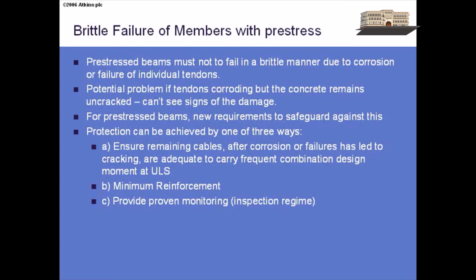As I say, if you've got very little pre-stress and a very large section, then basically when the concrete cracks, you've lost most of its capacity and there's virtually nothing left in the pre-stressing, so it might fail at the ultimate. If you don't want to do that calculation, then you have to put in more longitudinal reinforcement, basically, and there is a penalty involved in that because you have to put in as much reinforcement to basically fully cater for the loss of tensile strength, so you will end up putting more bars in there. So it's best to use method A.